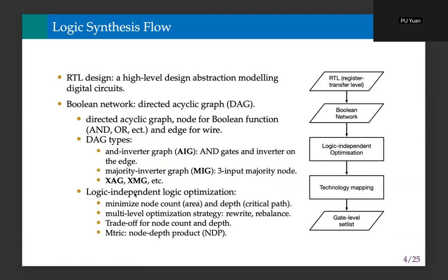For the logic-independent optimization, the main purpose is to manage the node count and the depth. There are several optimization strategies such as rewrite, rebalance, and so on. And there is a trade-off between node count and depth. So usually people will optimize the node depth product, NDP for short.